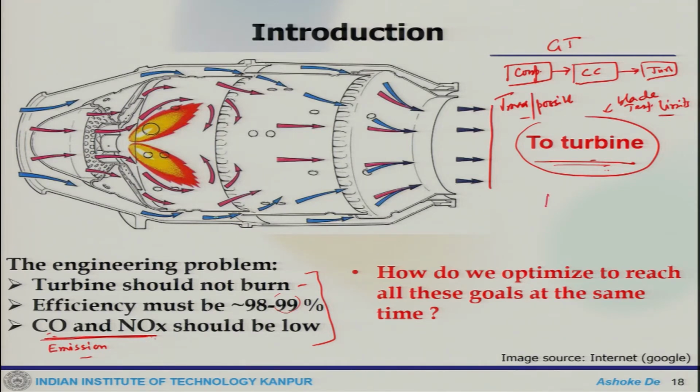So, if one plots the temperature axis against NOx and CO, at too high a temperature NOx will go up and CO will come down, but at too low a temperature, CO will go up and NOx will be low. So, even in the emission products there are different characteristics. It is a trade-off; one needs to operate a system within a bandwidth limit of temperature.